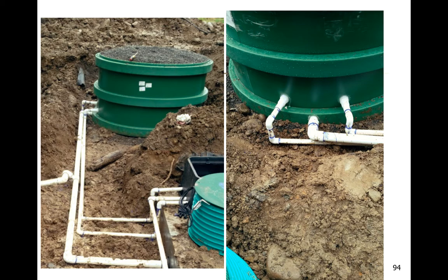Also, our 1-inch plumbing for our supply and flush line, because they're coming out in a sense square to the basin, and the basin being curved, they don't come out at right angles. So we strongly suggest that you use not 45s but 90s, where the first fitting either goes down or up depending upon logistics, and then a second 90 is installed so that now you can correct the angle, and now everything is going to be square in the trenches.